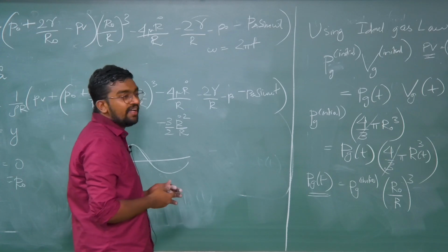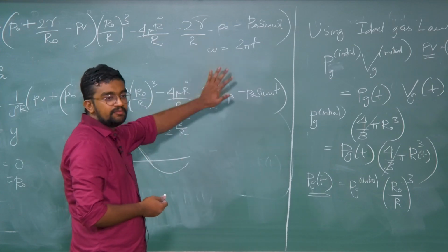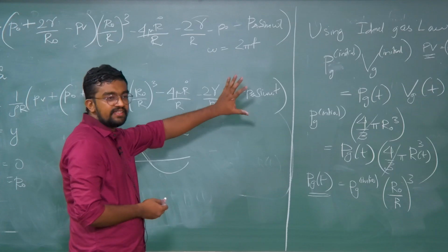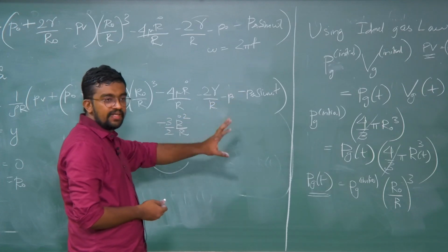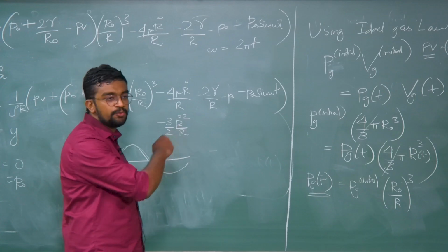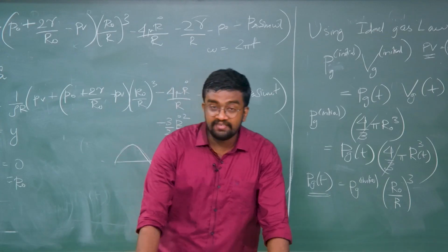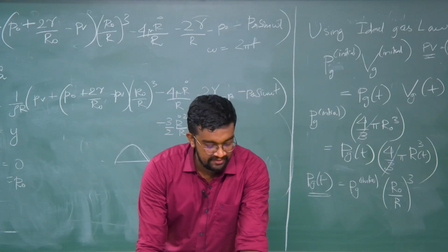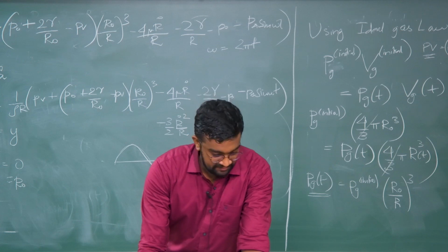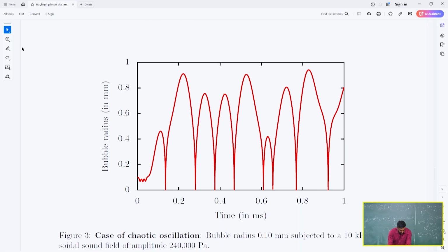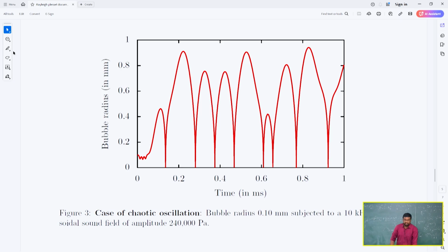So, we cannot have the wall deforming because the entire calculation is based on just unidirectional flow. The flow is irrotational and incompressible. So, there is no deformation of the interface. These are only artifacts of the second order nonlinear equation that we have. Okay. Now suppose we reduce the bubble size. If you reduce the bubble size or increase the applied pressure or PA, what we see is that after these wavy oscillations, you see a regime where there is chaotic oscillation.